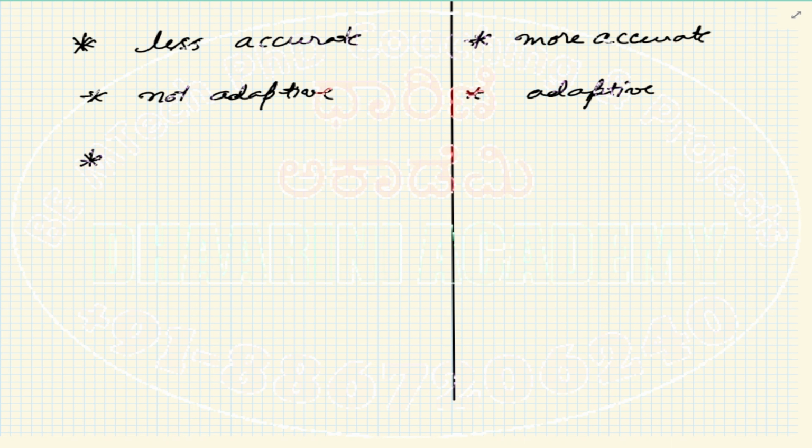One more we can add here is related to the linearity and non-linearity of the circuit. If non-linearity is present in the system, it will affect your output. So here the non-linearity affects the output of the system. On the other side, the feedback will take care of that, so non-linearity does not affect the output.